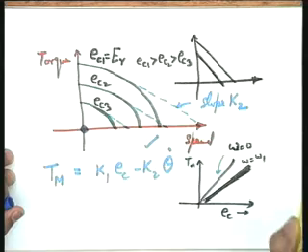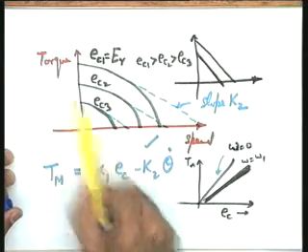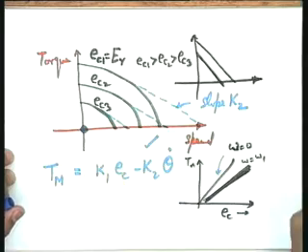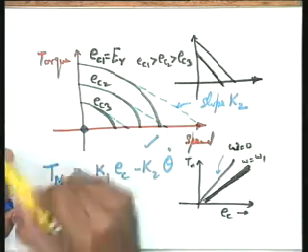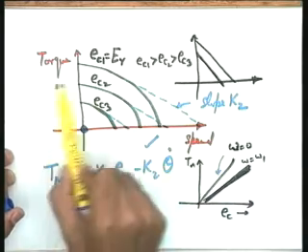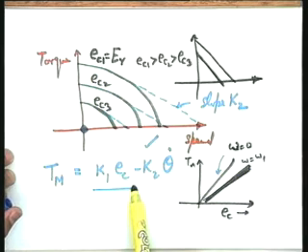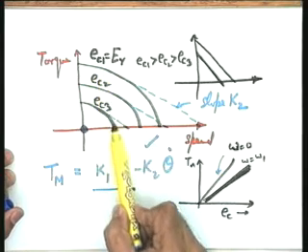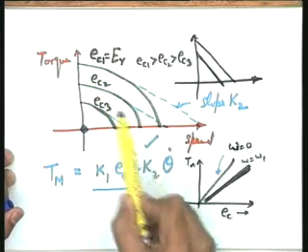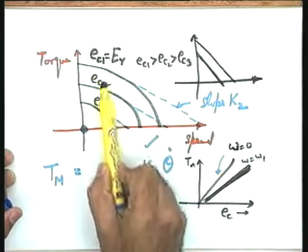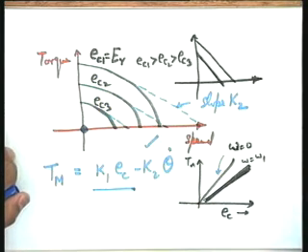So when you are experimentally determining the torque speed characteristics, this is an applied voltage to the control phase and need not be related to the error voltage, because then you are getting these curves for different voltages. What is the effect of varying voltage is coming through this particular equation. These are not the curves for a feedback control system. These are the curves you have obtained in the lab by experimentation, and therefore keeping a voltage constant for a particular experiment is in your hand. Is it okay?